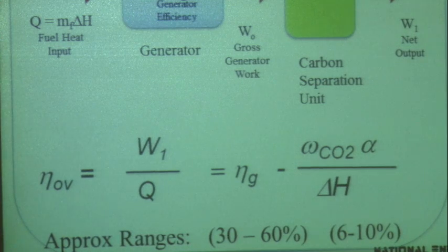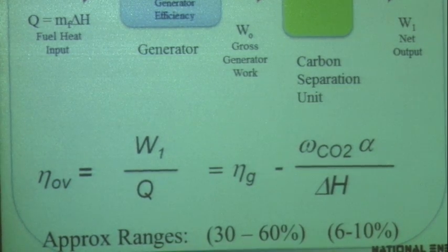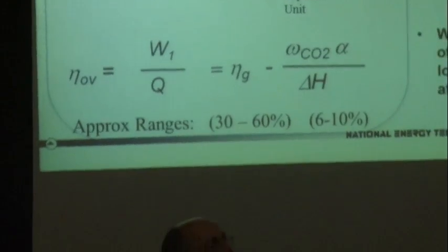And the steam cycles today, you're still getting a big exergy destruction getting down in the steam cycle. Even in the best systems, it doesn't even get to 700 centigrade. That's the highest temperature you're going to get in terms of the working fluid. Gas turbine is what? Really, really high compared to that. 1300, 1400, 1500, way higher for the top temperature.